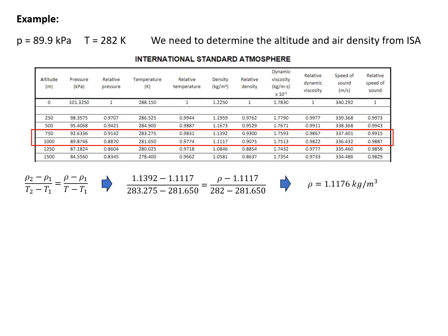Now let's first calculate the climb angle, which is arcsine of (T minus D) divided by W. We already know the thrust is constant at 260 kilonewton, and the weight can be calculated as mg, which becomes 1721.86 kilonewton. The question now is, how do we get the drag? We have the drag polar, and inside the drag polar we have CL.